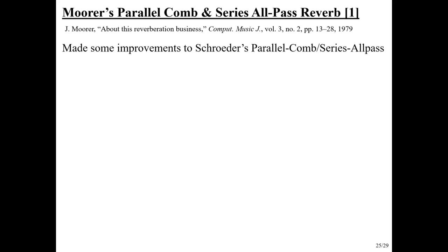Okay, so then what? Well, that was 1962. Remember, 1970, Schroeder published a paper that said, oh, let's tuck these early echoes in here, and we'll get that with a sparse FIR filter. And he even talked about using the output of that early echo to drive the late reverb. So that gets even more echoes. So you can certainly do that.